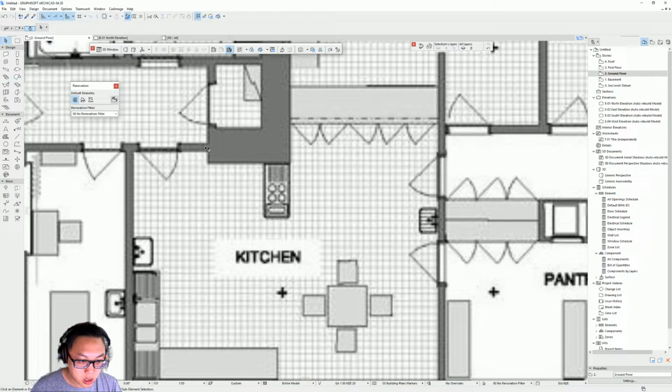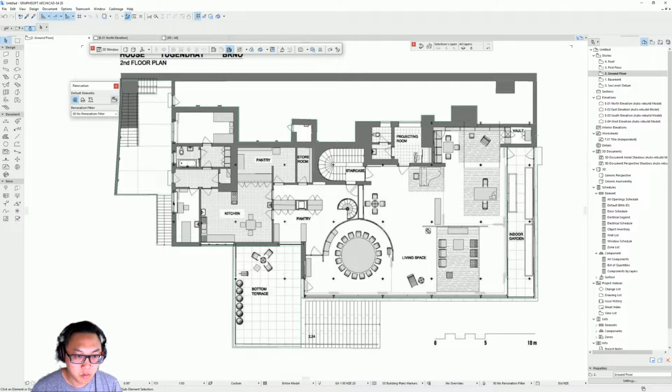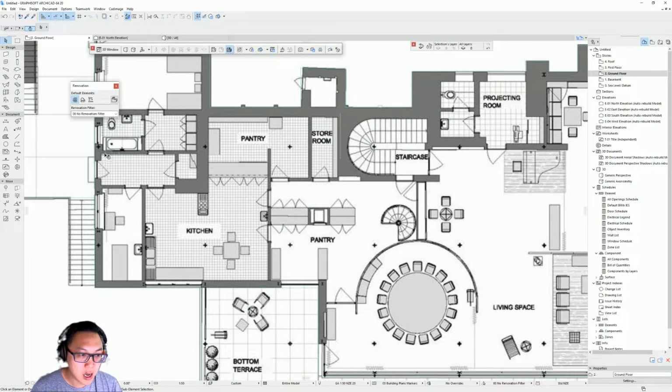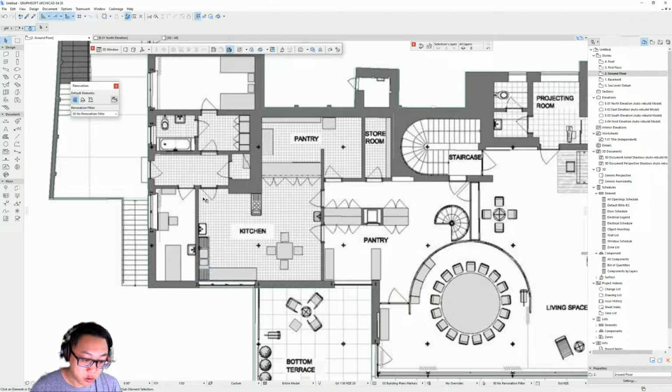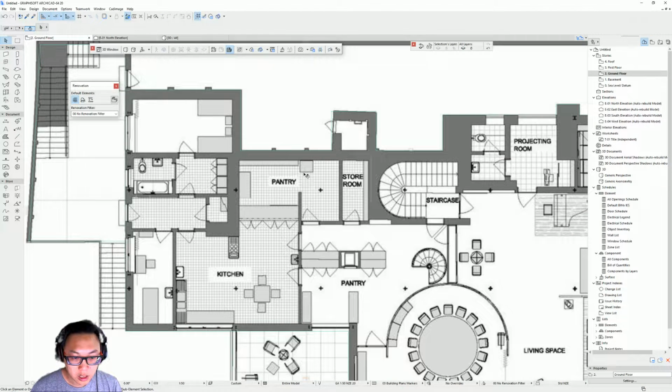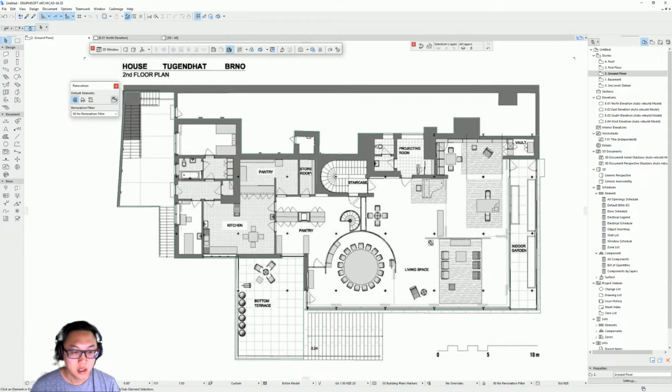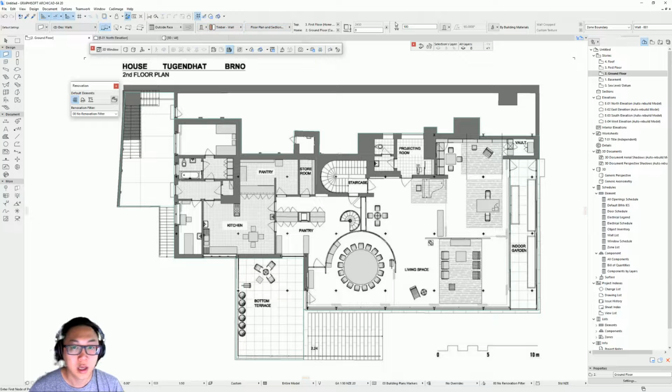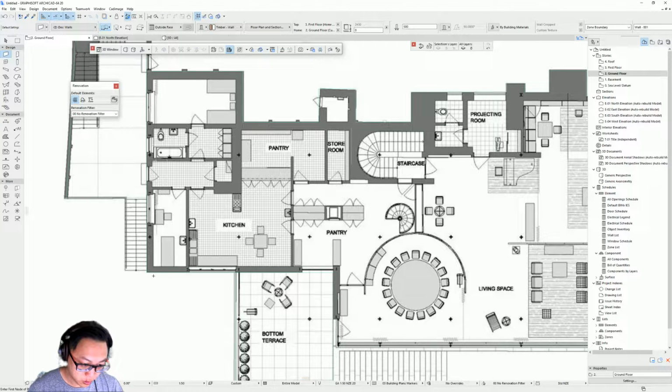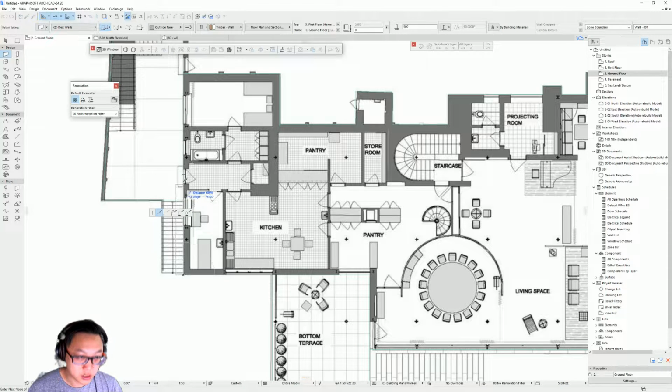And so what we're gonna do is we'll set the overall exterior walls as 200, and the one on the outside is gonna be 500, the one on the inside is gonna be 200, and we might tweak some of the bigger ones like those here. So let's do that. Take the wall tool, set it to 500. So I press the corner here, you can see the wall is on the wrong side, and you just have to flip it here, and now it's on the inside.